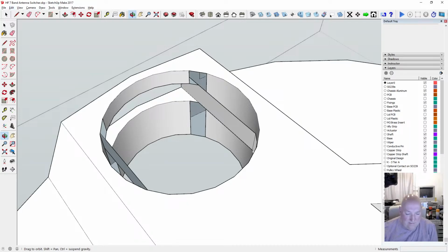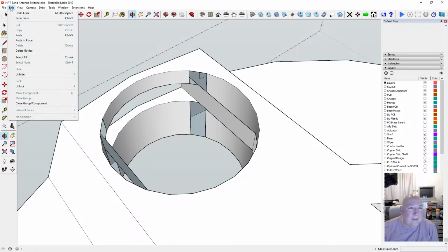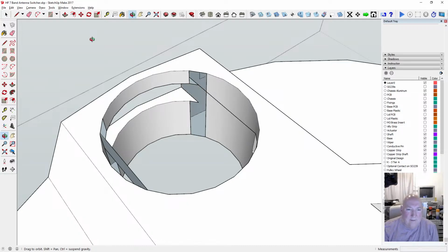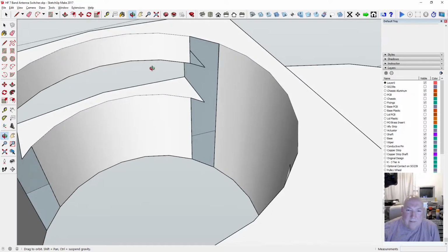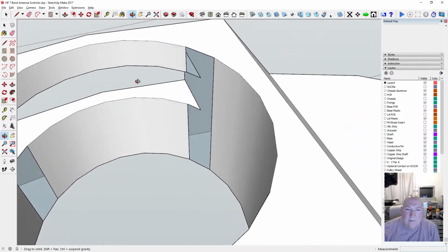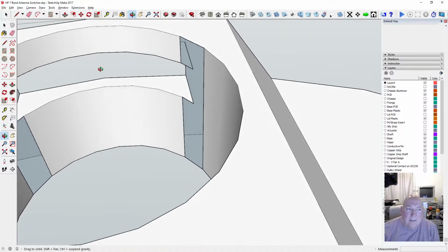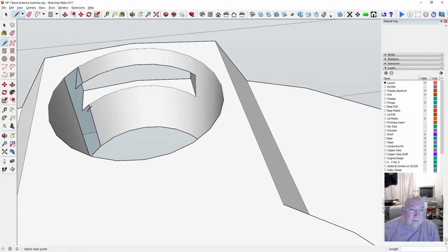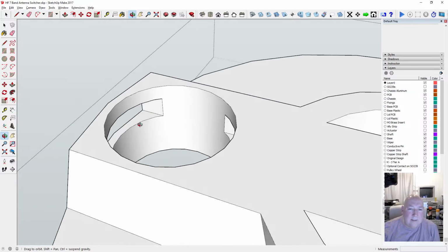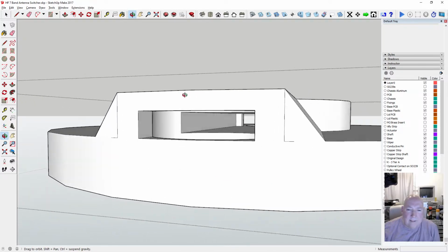Okay. Redo, Control Y. Right, so we lost it anyway. So all we need to do is join up. Yeah, join up that to there. Right. Yeah, and join up that to there. Okay, so we've got our surface back again, and yeah, that's okay.